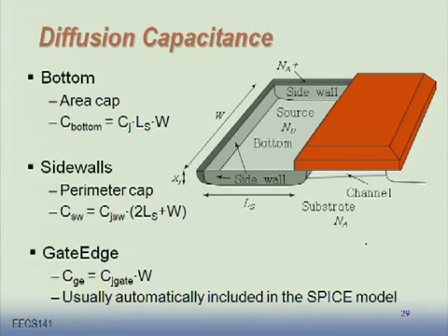But that junction capacitance, you can find out. The whole thing consists of the junction capacitance that has the bottom plate. There is a diode on the bottom of this junction and the substrate, and the sidewall capacitance. Along these sidewalls, there are little diodes all the way. So you'll find out that the bottom plate capacitance is defined per unit area. Sidewalls are given by perimeters.